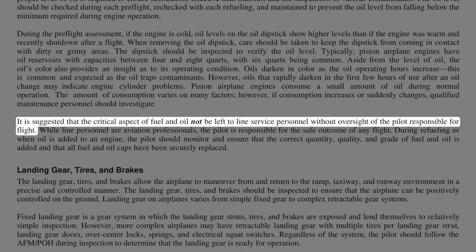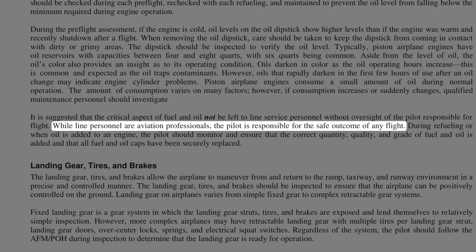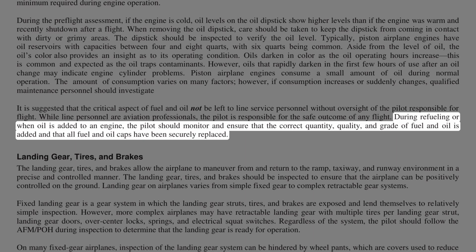It is suggested that the critical aspect of fuel and oil not be left to line service personnel without oversight of the pilot responsible for flight. While line personnel are aviation professionals, the pilot is responsible for the safe outcome of any flight. During refueling or when oil is added to an engine, the pilot should monitor and ensure that the correct quantity, quality, and grade of fuel and oil is added and that all fuel and oil caps have been securely replaced.